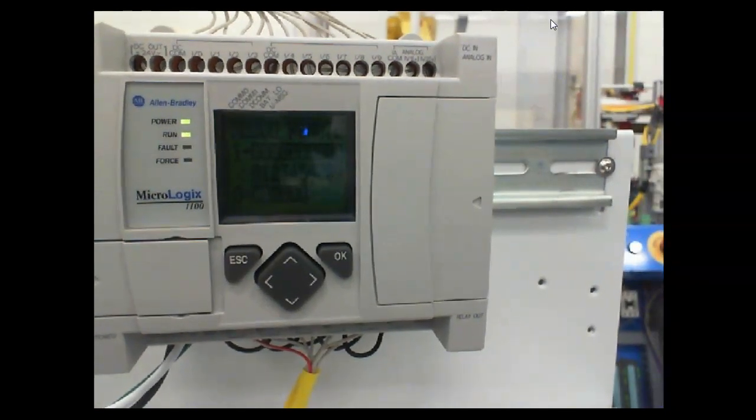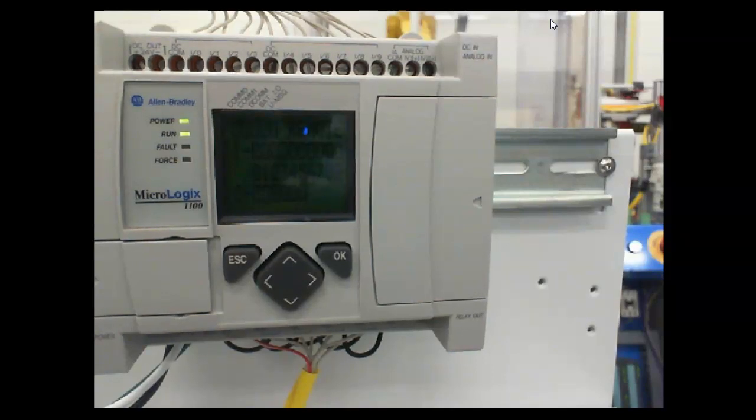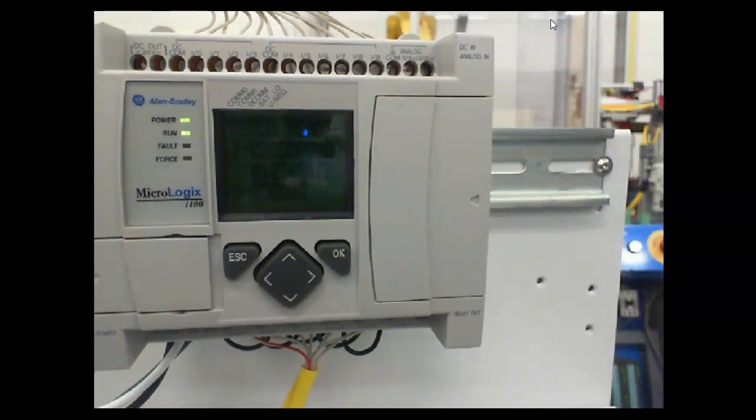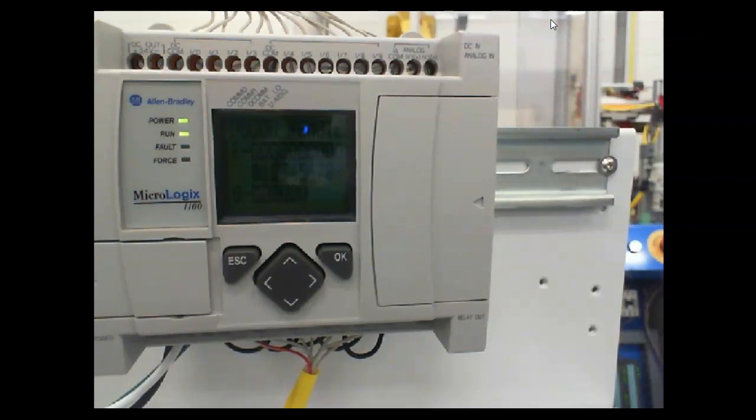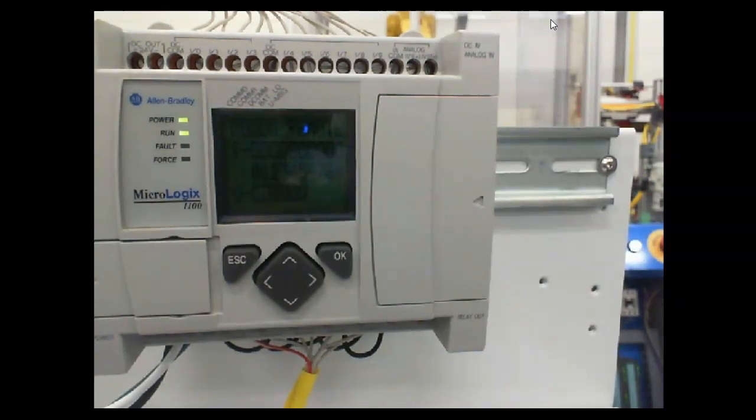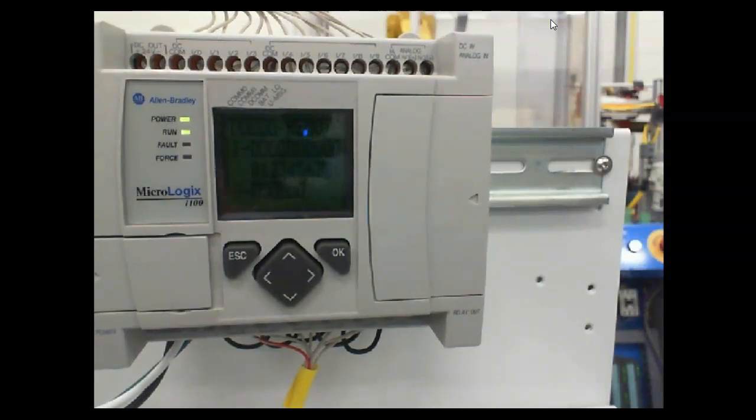For a lot of times, there was no definition on what voltage was lethal. The National Fire Protection Association, or NFPA, finally came out. They're the ones that wrote the National Electrical Code, which most people call NEC, that electricians have to wire houses by. The National Electrical Code is in there to protect the equipment. There's really nothing inside that code that protects you. So eventually, NFPA came out with a code we call 70E. 70E is a code that protects you.